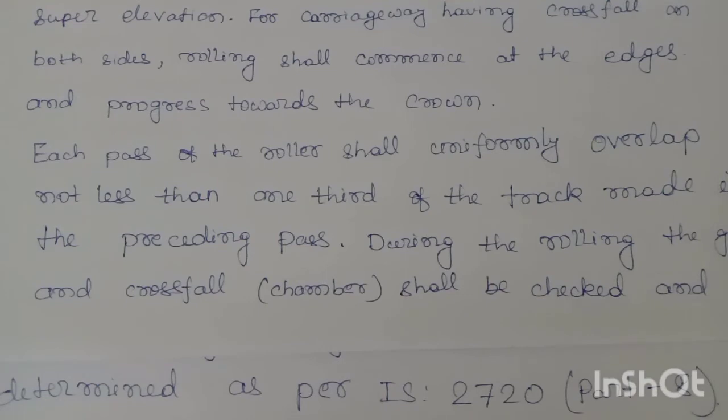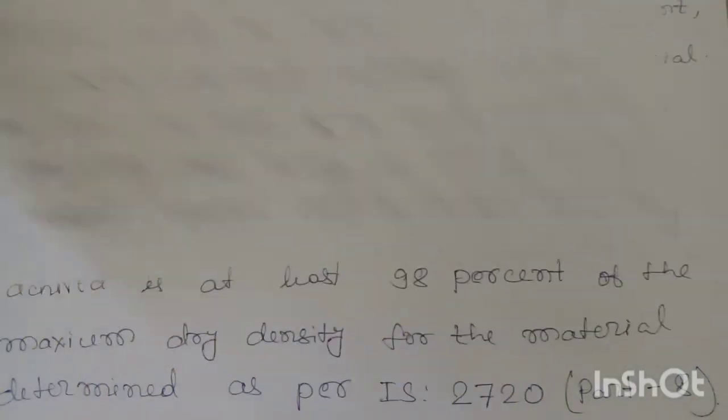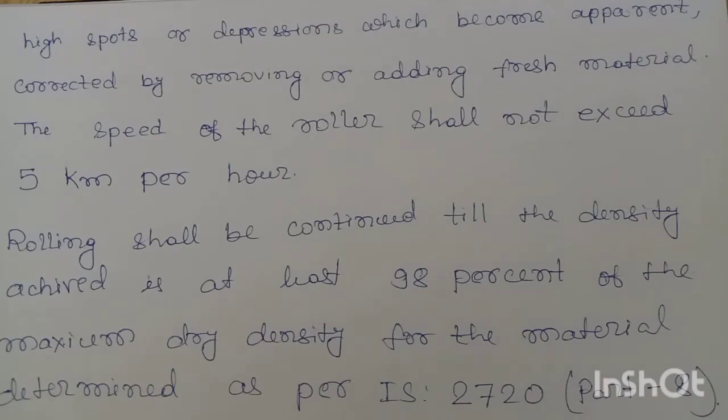During the rolling, the grade and crossfall camber shall be checked and any high spots or depression which become apparent corrected by removing or adding fresh material.